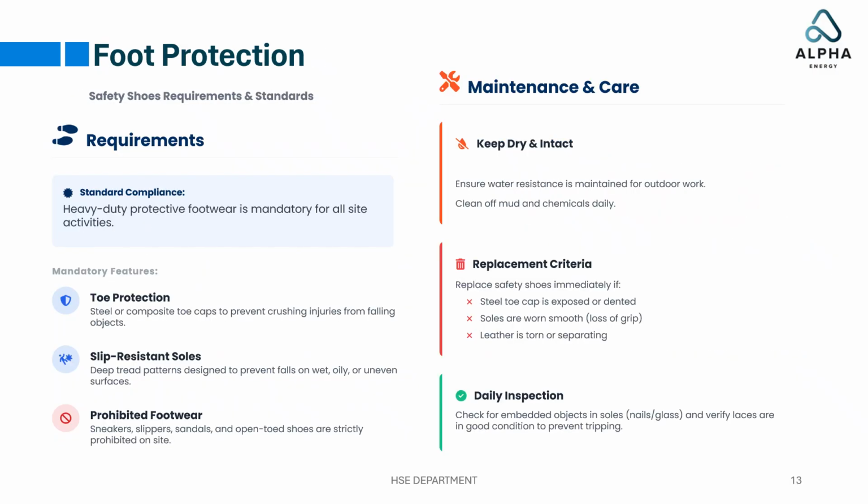Foot protection guidelines state that heavy-duty protective footwear is mandatory for all site activities and must include steel or composite toe caps for crush protection and deep tread, slip-resistant soles for uneven or wet surfaces. Prohibited footwear includes sneakers, slippers, sandals, and open-toed shoes.